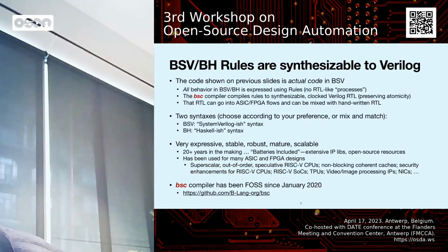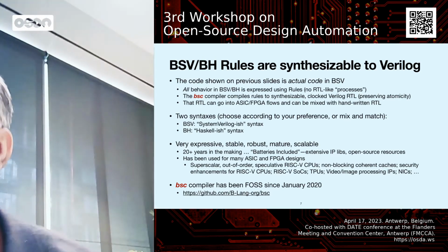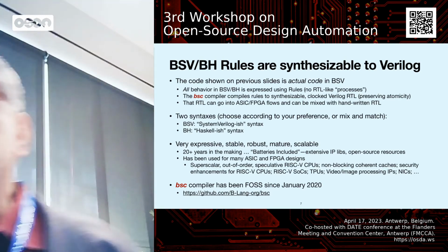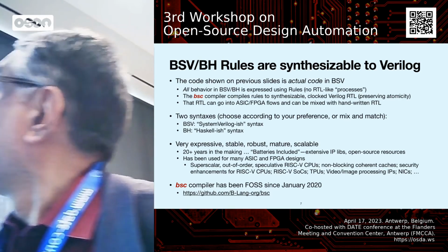So essentially the syntax and language I showed you in the first 2 slides is actual BSV code. I can push a button, run it through the BSV compiler, and get synthesizable RTL out of it. And that RTL, then you take it through standard RTL flows, FPGA or ASIC. And essentially, all behavior is written in this way, as in these formal specification languages. There is no other behavioral description other than this rule notation.